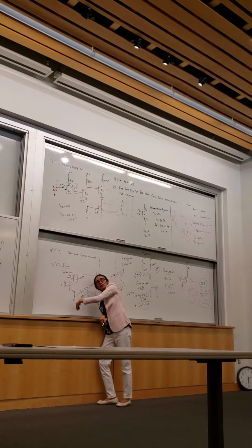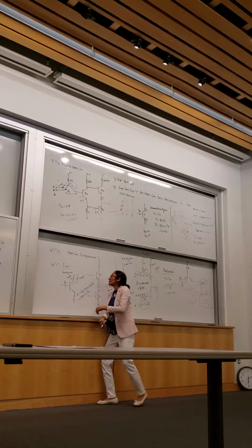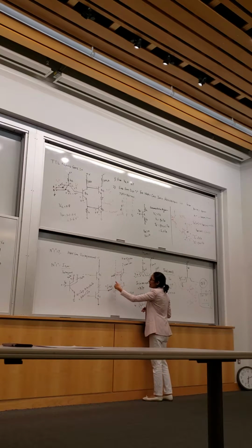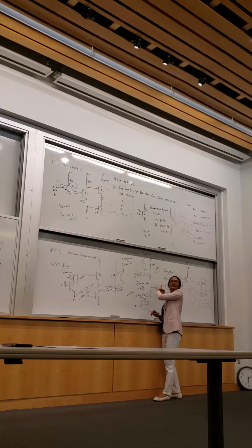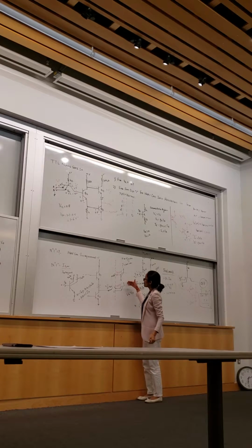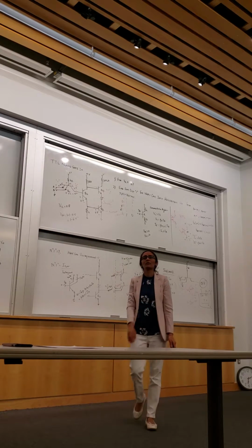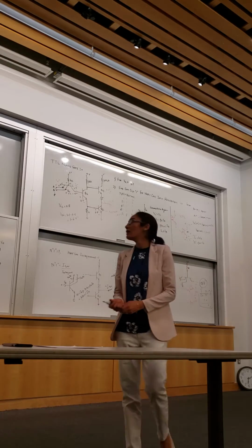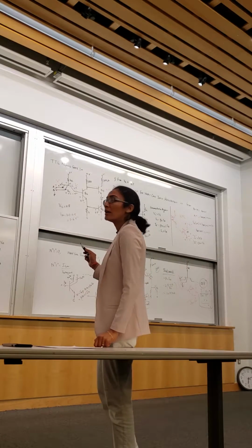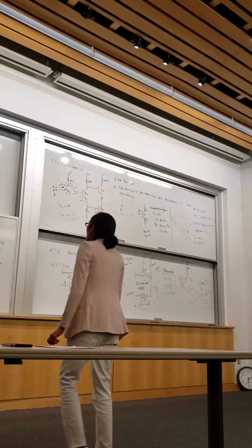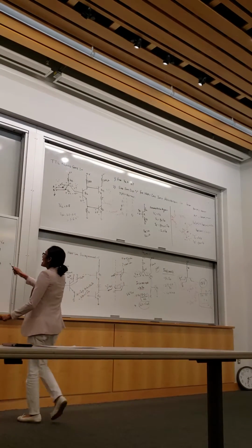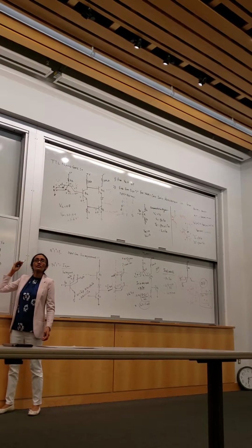It's going into the circuit. Okay. So when both are high, the current is going into the circuit. When both are low, the current is going out of the circuit. Okay. That's what you're asking, sinking, sourcing? Yeah, I'm just trying to understand and make sure the reason why we're dividing it in this situation is because the current is flowing through both of the inputs and not in other situations, because everything else is off.